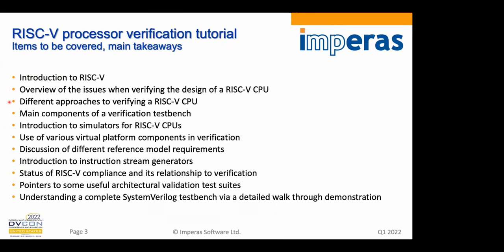We're then going to drill down into different components in verification test benches, introduce some of the simulators available, both free and commercial. Then we're going to talk about the different components that you might need in your virtual platforms or your simulation for your verification. We're going to talk about the reference models that are available out there and the capabilities that are needed, introduce tests and instruction stream generators, talk a little bit about verification in relationship to compliance, and provide a detailed walkthrough of a SystemVerilog test bench verifying an open source core.